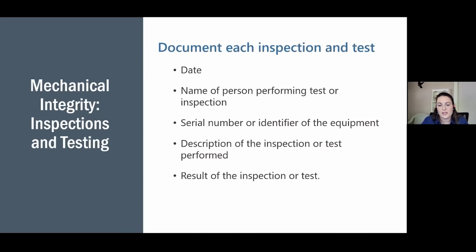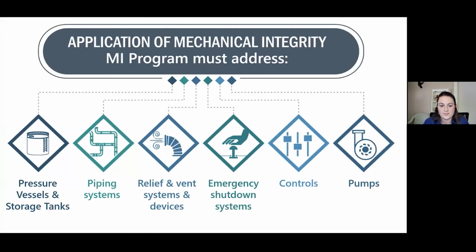The easiest way to develop the schedule is to review the operating and maintenance manual provided by the manufacturer for each piece of equipment on the process. That's where you want to start. Listen to their recommendations, pull that into the schedule. Then there are industry tests like ASTM, the Steel Tank Institute, known as STI, and National Fire Protection Association, NFPA, that will provide additional guidance on routine maintenance of process vessels.